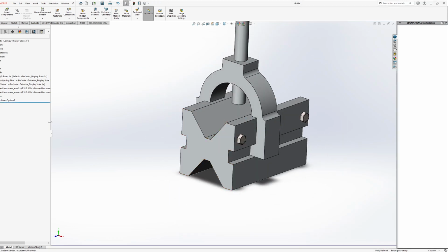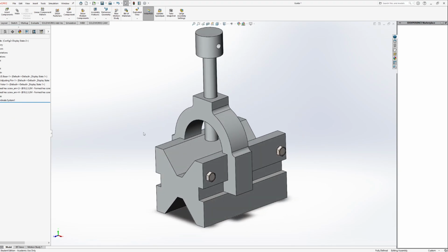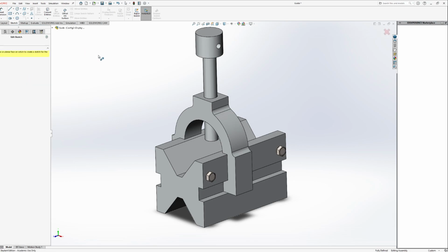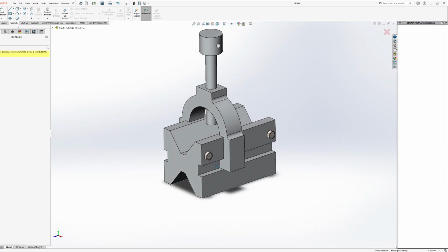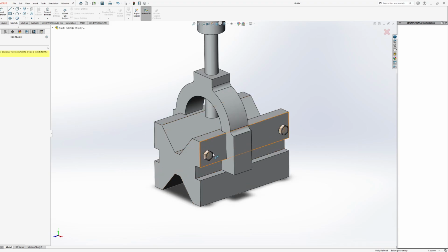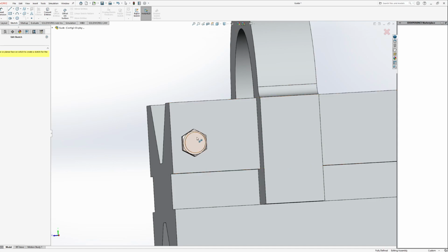So the way that we can get around that is just like how we can add reference geometry to parts or components or drawings or any of that stuff. We can actually sketch in assemblies as well. Now, forewarning, I wouldn't recommend doing it often because assemblies is where you should be putting parts together, not creating new ones. But in terms of reference geometry, creating sketches is a good way to create extra reference geometry. Also, I want to choose something that really isn't going to move, because having a moving coordinate system is going to be bad news for everybody.